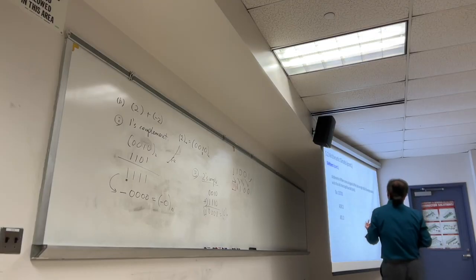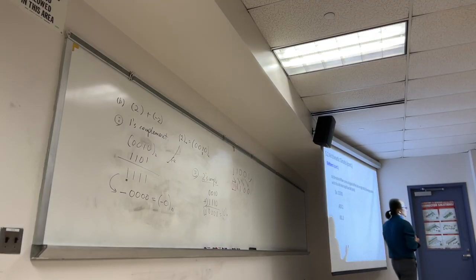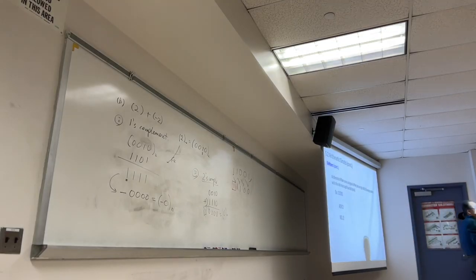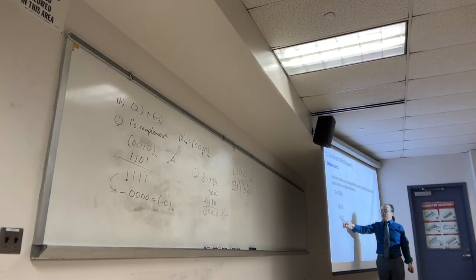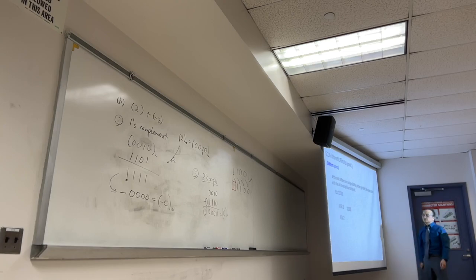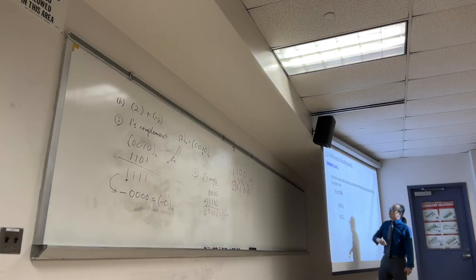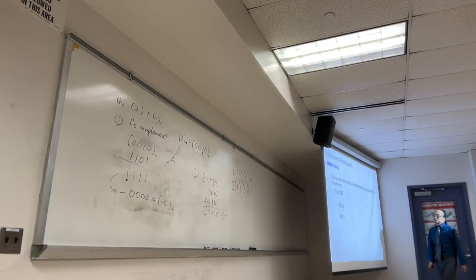For the arithmetic shift to the left though, the sign doesn't matter because we shift to the left into the lower bits. So this is basically the same as logical shift left by 2. It's exactly the same. Now, the rotator. There is ROR and ROL, rotate to the right, rotate to the left by 2 bits.